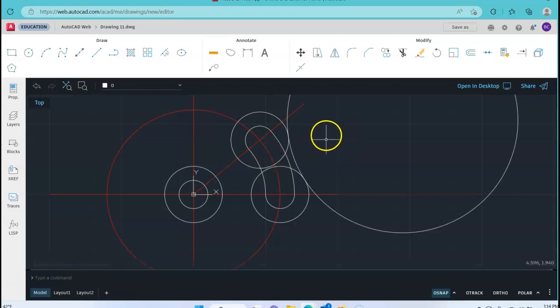And notice, see what happened there? My cursor was on this side, so I let that drift while I was kind of going through stuff. So let's kind of come back here for just a second. I'm going to go back to the circle command, TangencyRadius. So I'm going to pick up on this one and this one, and I'm going to make sure that I'm over here with my radius. Again, 4 is automatically in there, so that's just good. So I'm just going to click enter. All right, still didn't quite do it right.